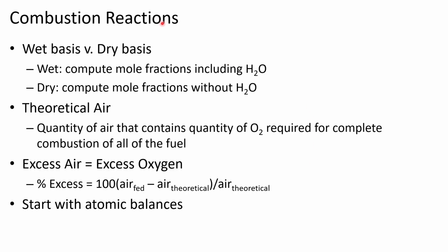Of course, with combustion reactions, we're going to have a whole set of new terminology to deal with, and those terms are summarized here. The first and probably most important one is that we'll make a distinction between whether compositions are specified on a wet basis or a dry basis. The difference is stated here. When compositions are specified on a wet basis, that means the mole fractions have been calculated including water in the calculation. When mole fractions are specified on a dry basis, that means that water was not included in the calculation. And we're going to see an example of this in the very first problem that we work.